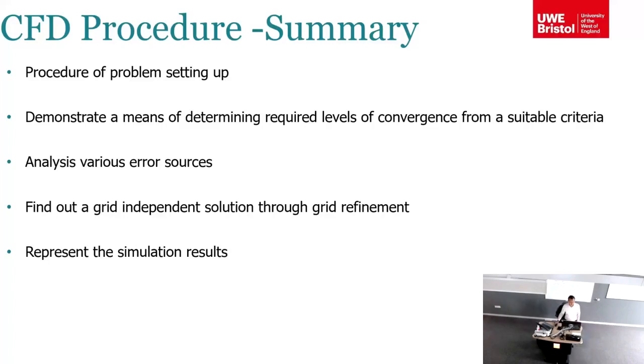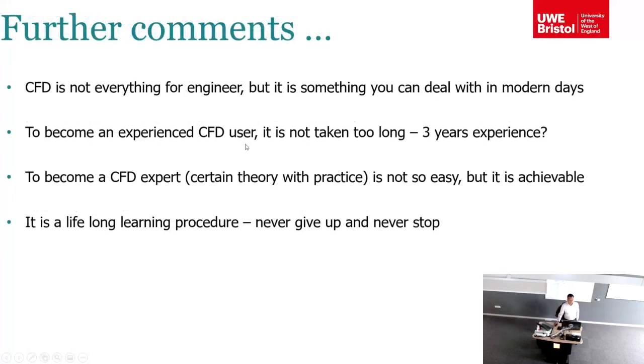Set up the problem. Set the levels of convergence. Analyze and look for errors. Do a grid independent study, and represent the simulation results. Okay, and some final remarks.